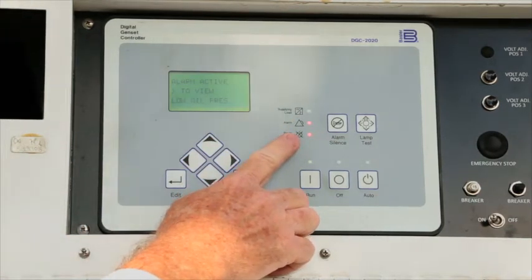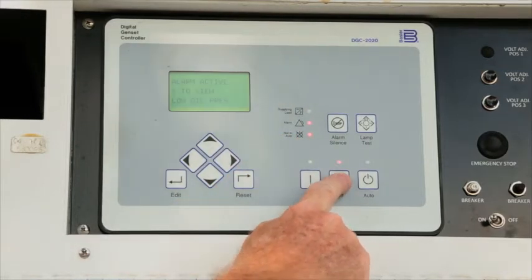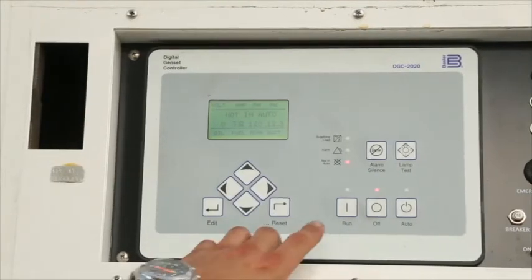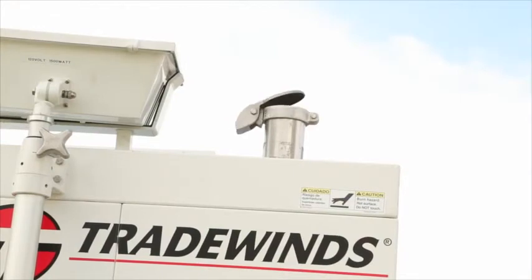Having corrected any fueling or oil issues, the operator has to clear the alarm by pressing the off button as indicated. Pressing the off button will also clear the alarm display light as indicated. Having now checked the most common reasons for failure to start or shut down, the generator is now ready to run.